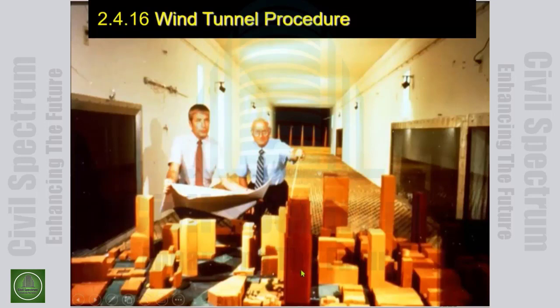So this is the building that is being tested in the wind tunnel. Typically that building will be modeled in wind tunnel testing. The scaling down of the buildings is the most important thing. So you typically do not test only the building, but essentially the neighborhood, because the neighboring buildings affect wind flow on your building. And you also can play what-if scenarios.